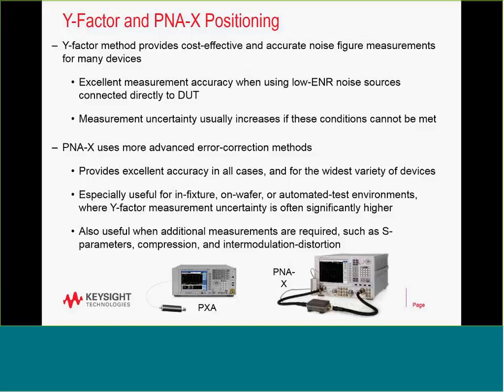The measurement uncertainty, unfortunately, goes up a little when you start working farther from the device. For the PNA-X, with its more advanced error correction method, we can provide excellent accuracy in all cases of measuring these devices. It's especially true for in-fixture and on-wafer, because we can calibrate all the way out to the device under test.